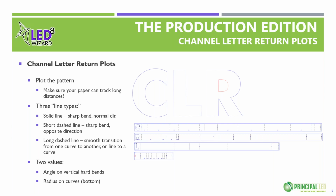Now, if you had a halo lit letter and you wanted this pattern to bend and mount behind the face, you can do that, but it's a little bit of a hack. The tool doesn't take a negative value for an offset, but you can negatively offset the letters before you run the tool and essentially achieve the same thing. It's a little bit backwards the way to do it, but you can do that so that the return isn't on the outside of the face, so it's behind the face.